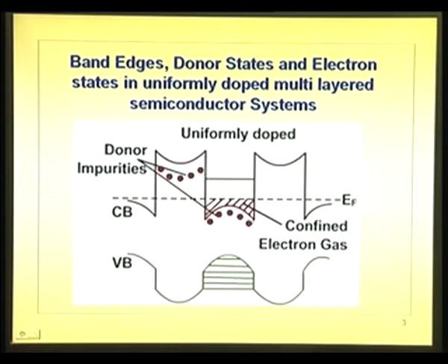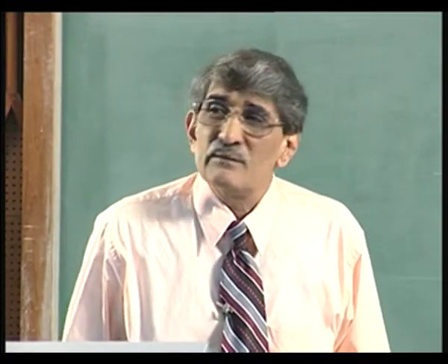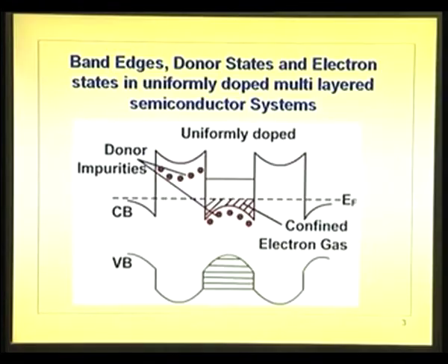And these are also donor impurities. They are both N and N. It is not N and P. What we discussed last time was N and P, but N and N, that is a different type of heterostructure. Isotype, the other one is anisotype. So, you can still make heterojunctions with this.